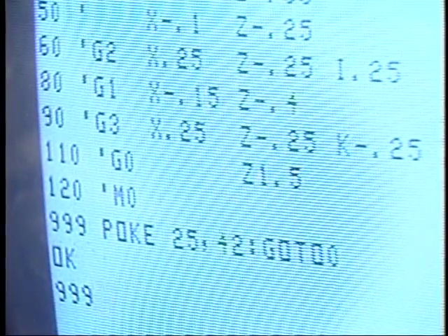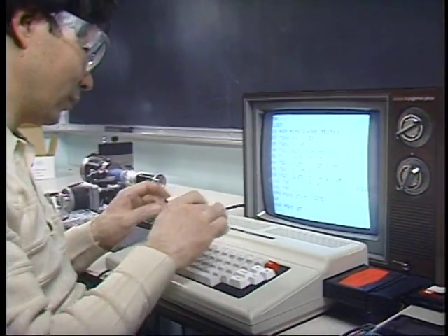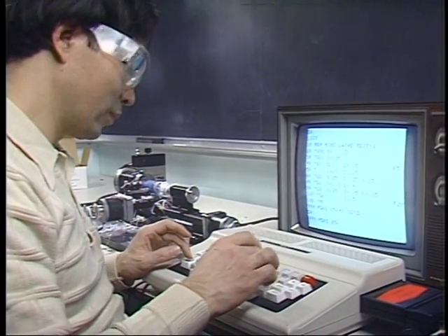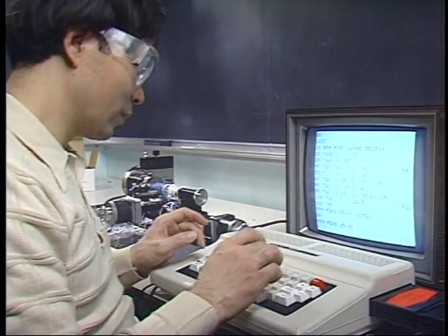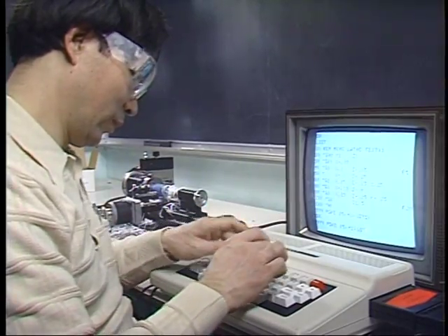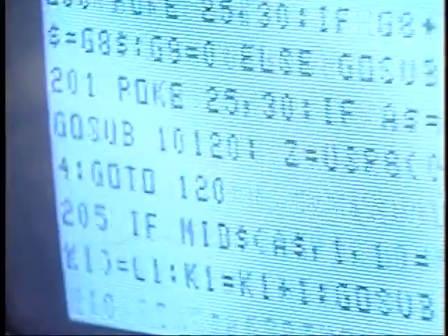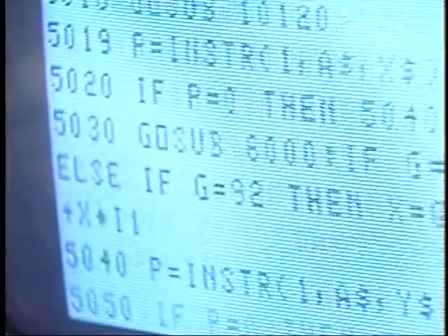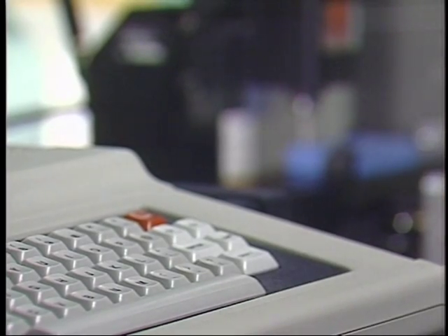The computer supports additional functions such as offline programming, program editing and verification, and links with CAD databases to allow automatic program generation from part geometry. Also possible are smart editor programs which check part program statements for syntax and logic errors prior to attempting execution. The part program may be executed on the machine tool or stored on tape or disk for future use.